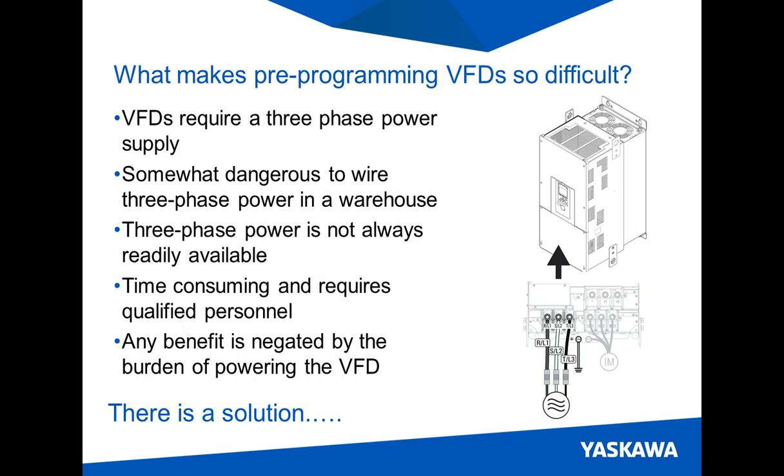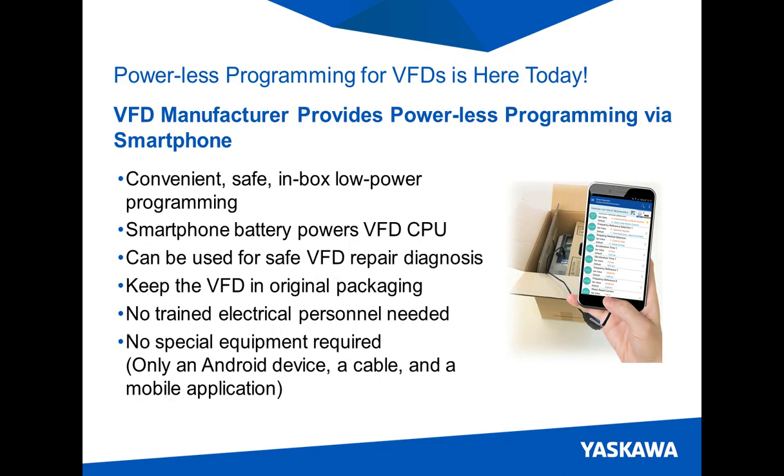Recently, one manufacturer offers a solution using your handy smartphone for this. It's now possible to program the VFD with your Android smartphone without applying dangerous main circuit voltage. One manufacturer uses a USB cable and a mobile app on your smartphone to power the VFD's processor for programming while it remains inside its packaging.